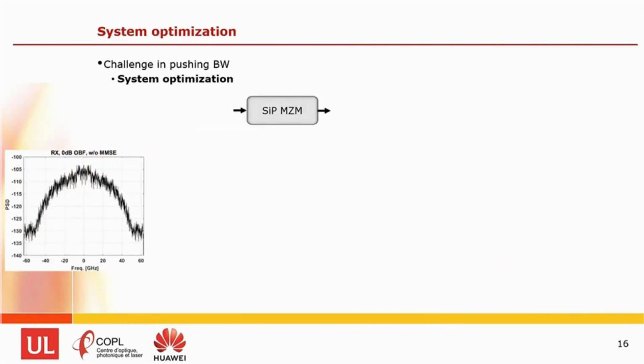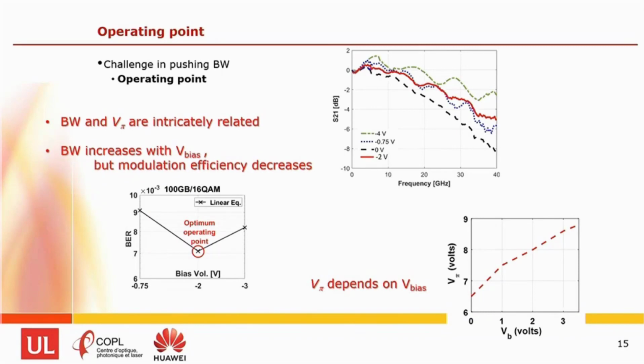Then the next, I should point out, this is the small signal model. And of course, when I'm operating my modulator, I'm making much larger swings than what is involved in this characterization measurement. Because of that, you can tell that the modulator intrinsically has a nonlinear response, because the frequency response will vary depending on how I'm driving. As I swing through the 2 volts, for instance, I'm going to go through the equivalent of different bias points, and that's going to change the frequency response.